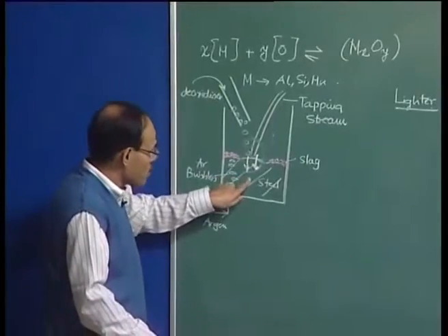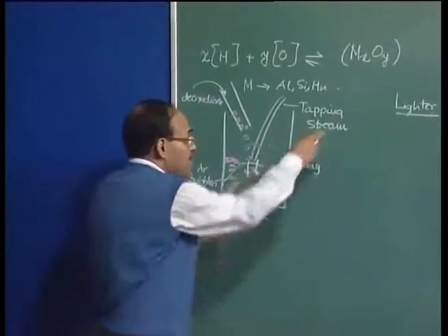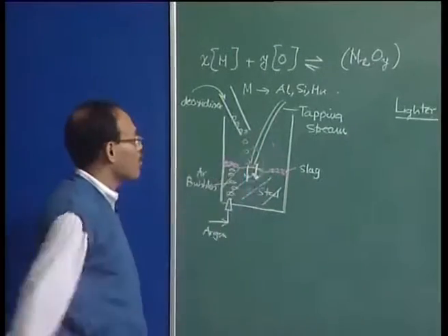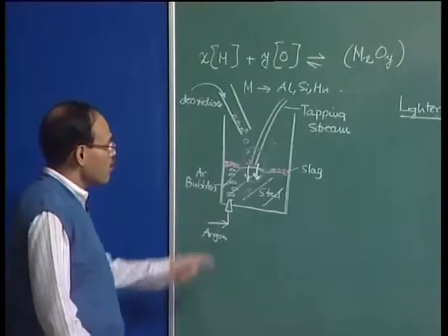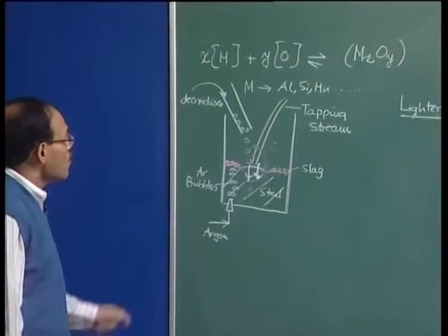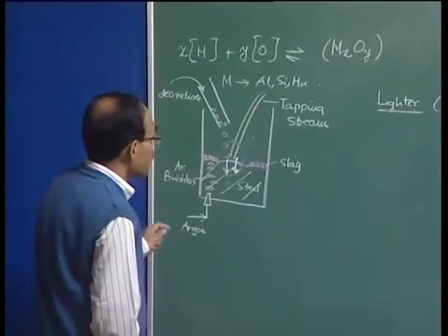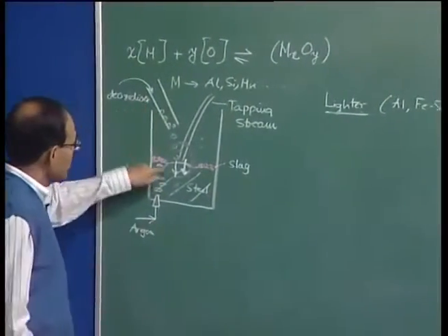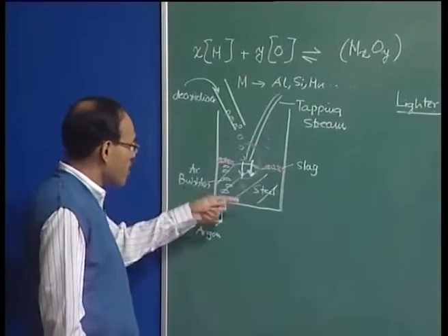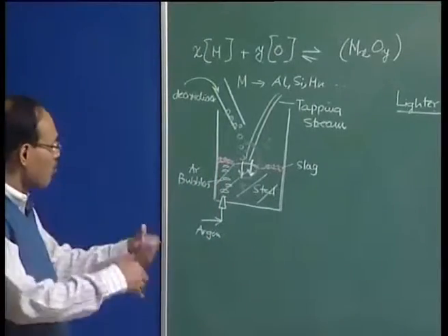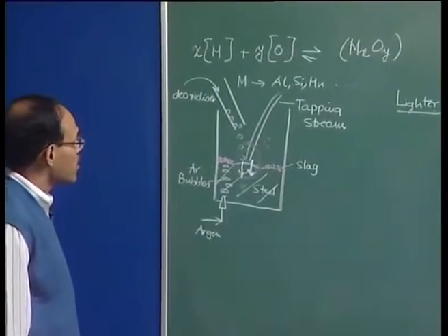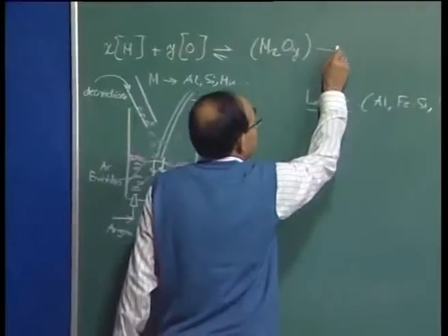Okay, from this part to this part, the oxides are always lighter. That is why the oxides of the slag is going to float up, and the amount of the slag is going to be progressively building during the process of ladle filling operation as well as deoxidizer element addition. So, deoxidizers upon their entry into the bath will spend some time subsurface, and then in the process of that they are going to react, they are going to melt and dissolve, and react with the bulk steel oxygen in the bath steel. So, this we say is the deoxidation product.